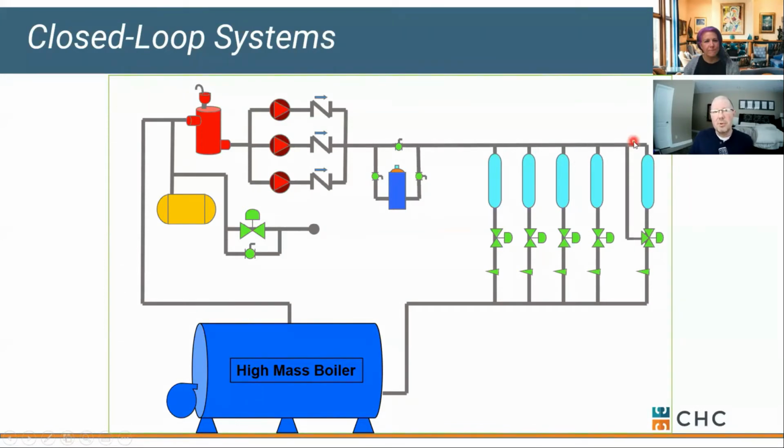Most of those are controlled with 2-way valves. You may have a 3-way at the end to maintain some minimum flow. So when we come back cold into a boiler, we pick up some heat and we bring that back to our system pumps, where again we transfer that energy and we send low pressure and create high pressure with our pumps and distribute that water flow out to our building, out to our system, okay?